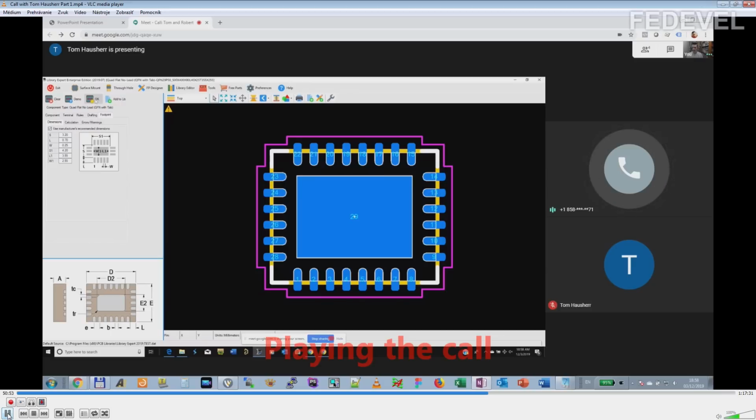They got to put their chip on a board, then they got to run their board through all kinds of stress tests: thermal shock, thermal cycling, vibration tests. They got to run all these tests, and from these tests figure out what is the best land pattern, or what is the best pattern that we should use?